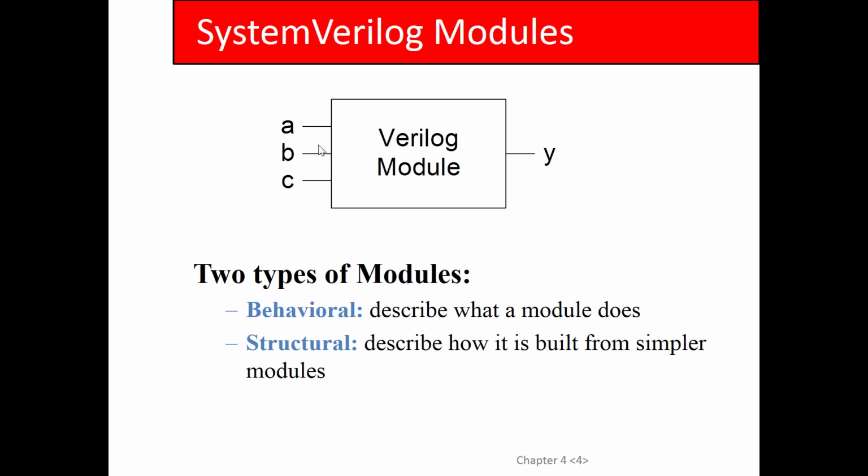But when you synthesize your circuit, the hierarchy gets flattened out. So the whole design hierarchy is only there for the purpose of your design process, but when you convert it to hardware, ultimately the whole design gets collapsed down to one flat sea of gates and wires. You guys with me?